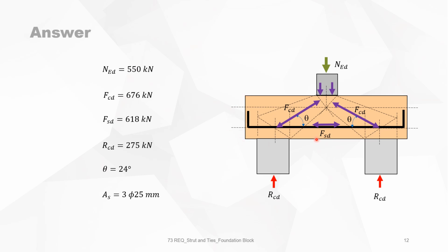We did not talk here about the minimum reinforcement in the total block, and we did not check the tensile stresses in the compression struts, because this compression strut has a smaller cross section on top than on the bottom, so they are fanning out, or they disperse. And this dispersion gives rise to tensile forces. It was not checked in this exercise.